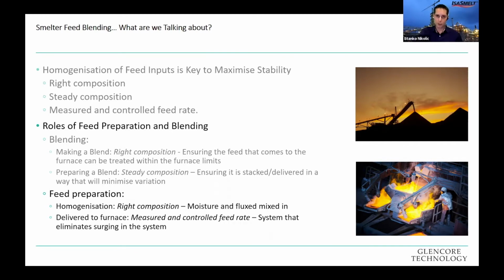If you have large amounts of moisture, regardless of smelting technology, that can result in a fluctuation in the pressure in the furnace, and that's something that will have to be handled by the gas handling system. So that's where the advantage is of the stationary closed seal furnace technology like the ISASMELT, where you're able to deal with these pulses within the system and minimize emissions to the environment.